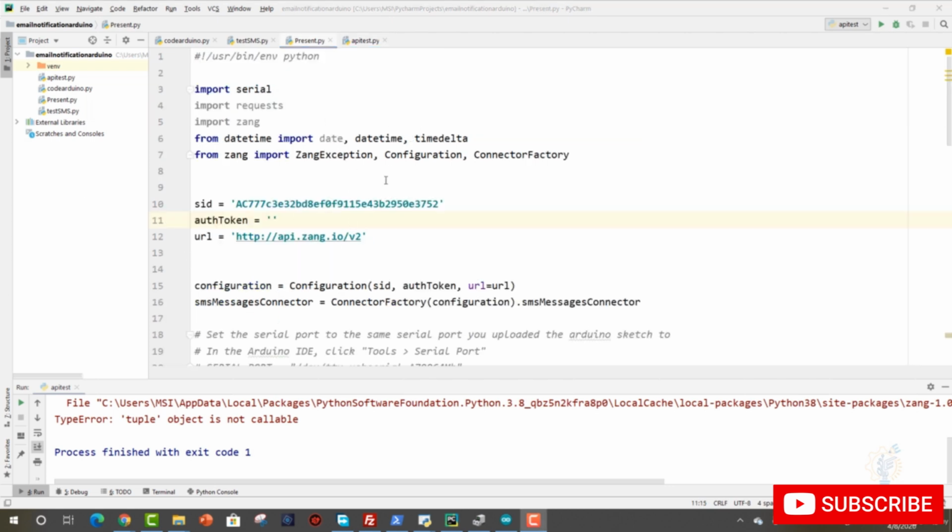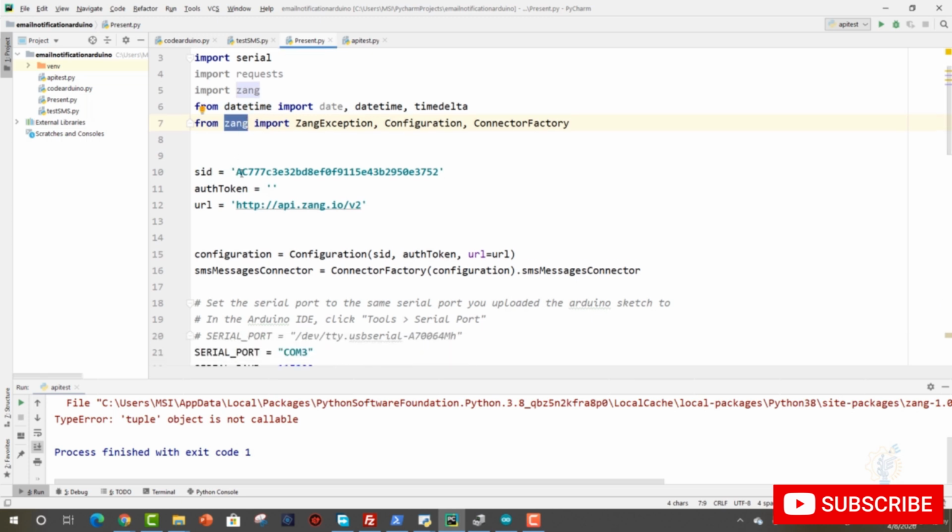Now this is the final code that we are going to use. I have implemented the API code inside this code so that we can communicate with Arduino, read data, and check this data. As you can see, we first imported the serial library because we are going to communicate with Arduino using the serial port or the USB serial port, and we have imported the same libraries, date and time, and Zang for SMS notifications. This is the SID from the Zang website, which is the SMS API website, and here you need to paste your authentication token.